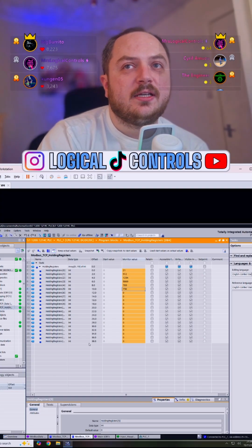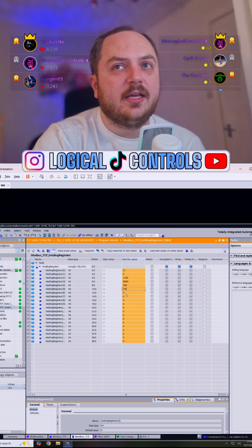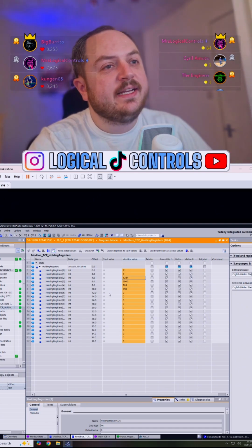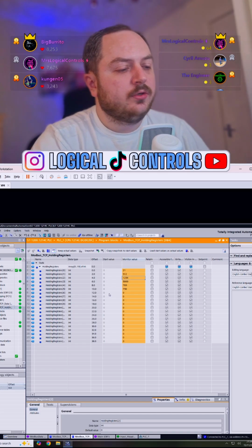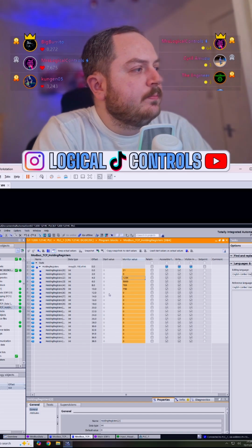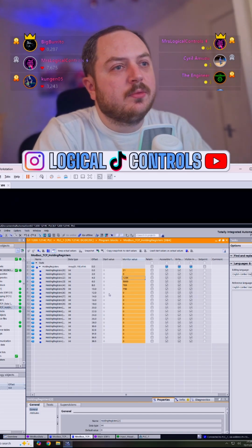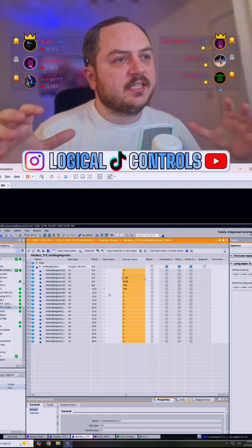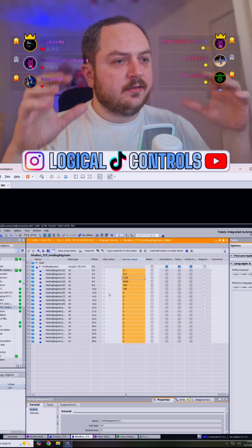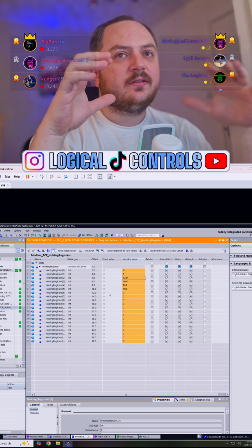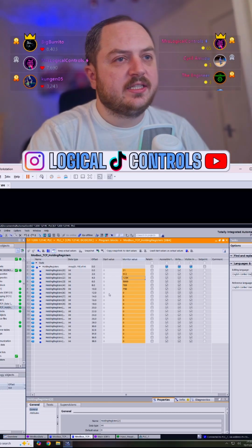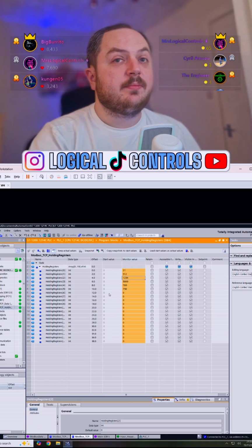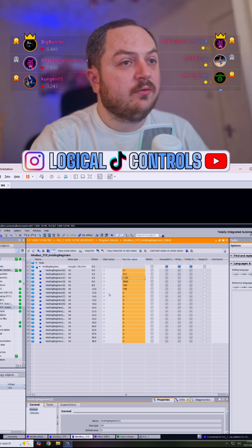Yeah, all it is, these registers exist within the Siemens PLC. We're able to read that data out. So if you think of a SCADA system or a BMS system, some higher level system which looks at a site or a process as a whole, you need to feed that with the data. That needs to know what's going on with these different devices. So you might have these little local PLCs everywhere, and Modbus TCP is a good way of pulling all that data out from these different devices.